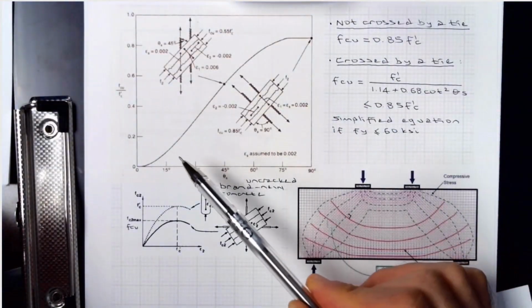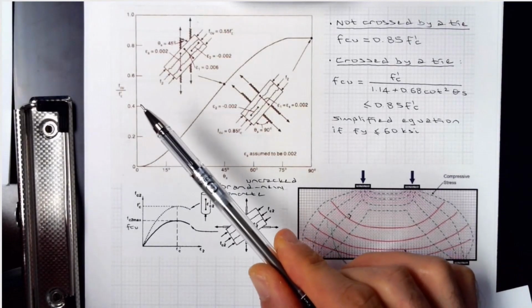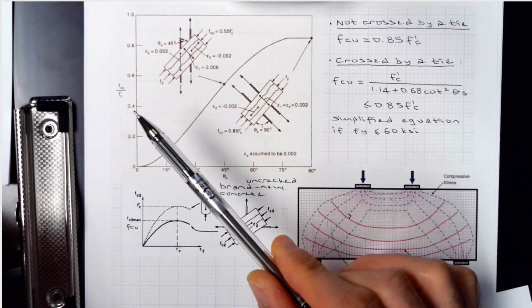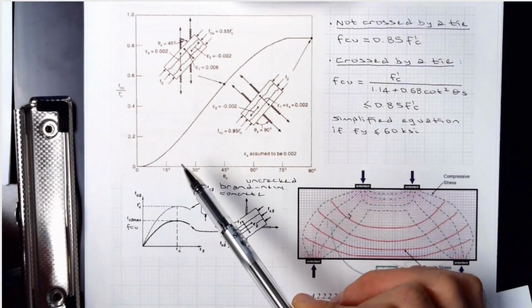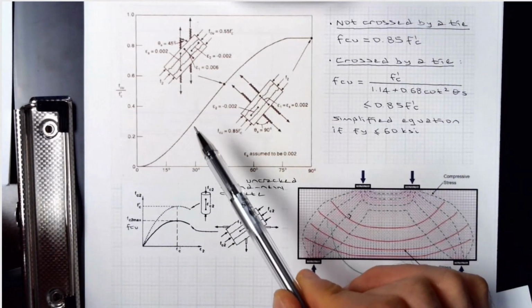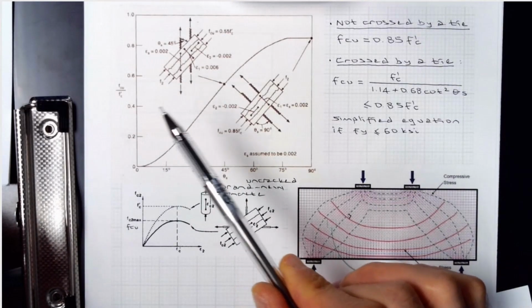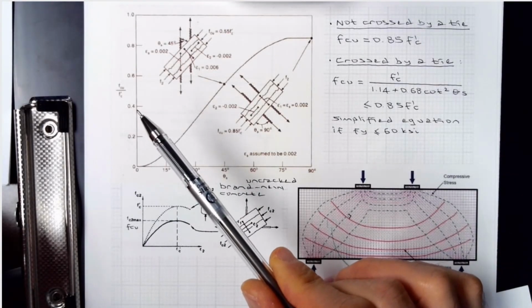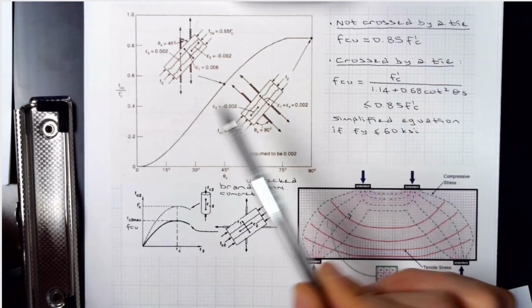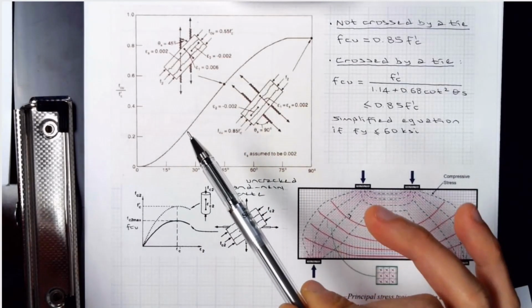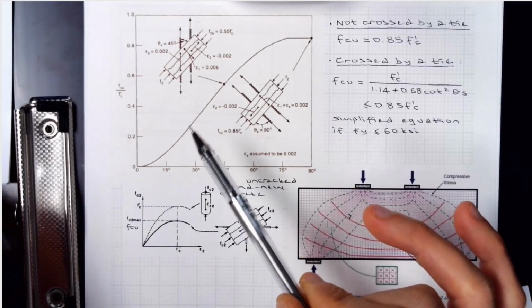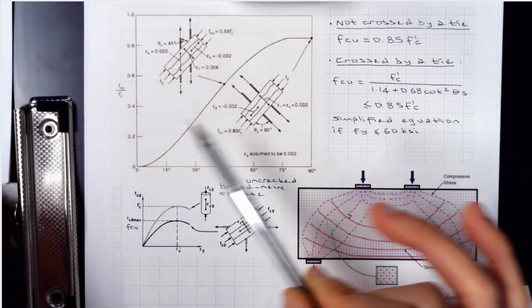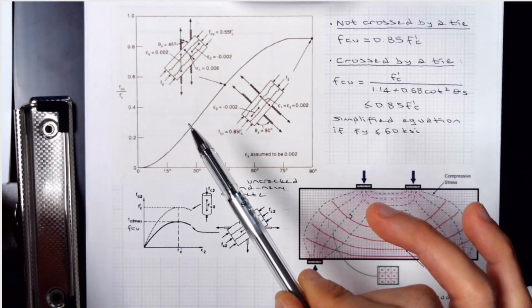So that is theta, as you can see from this plot, significant penalties to your capacity. The multiplier, you might reduce it to 0.4, 0.2 if you have really bad thetas. H2 limits this with 25 degrees, which is here. So probably you might get around this number as the worst case situation, but it's a major reduction. So if you get that theta shallow, then you're developing your model. If you see shallow angles, that's not a good sign, because it's going to have some issues down the road when you come to that check later on.